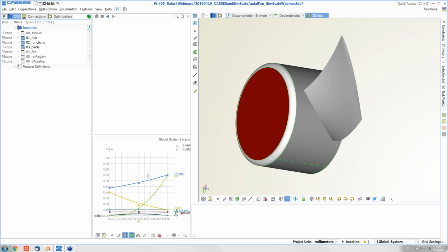So for the fan blade, this would mean increasing the pitch. That's the one thing. And another thing that comes to my mind is that we can increase the camber of the blade profile, so that we can also generate more lift or more flow from the fan. So these are the ideas that I have in mind. So let me show you now how to create these variants.